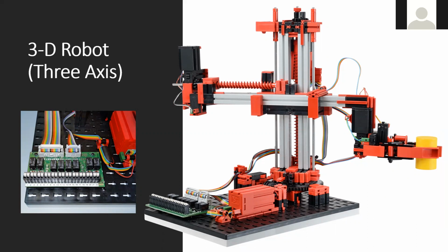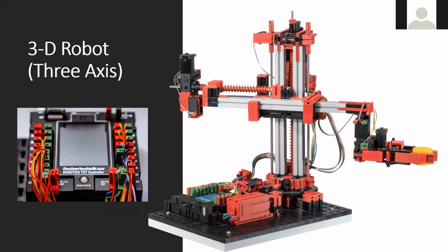Components on this model include 2 XS motors, 2 encoder motors, and 4 push-button limit switches. Dimensions of this model are approximately 19 by 16 by 9 inches, and it has a weight of about 6 pounds. And again, this comes in either a 24-volt version with a 26-pin connector and 2.54 millimeter grid, as seen here, designed for use with the PLC and programming of your choice, or in a 9-volt version, which in this case is not a limited availability model, but is a standard model as well. And once again, this comes wired to a pre-programmed robotics TXT controller, and it requires one 120-volt power adapter.